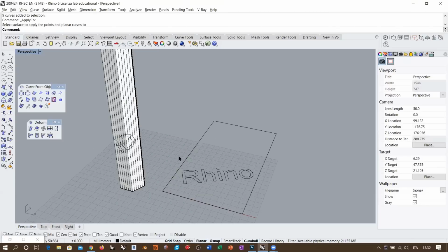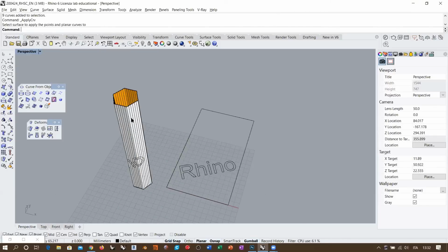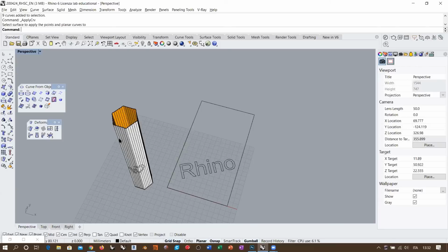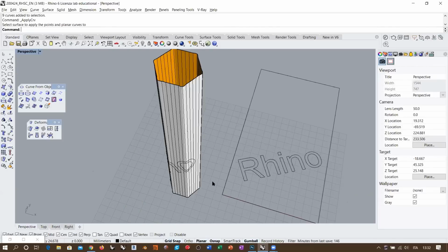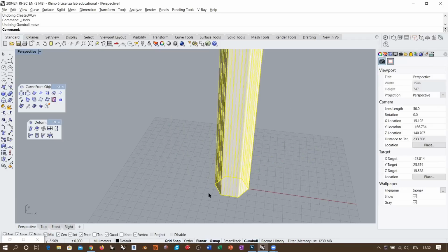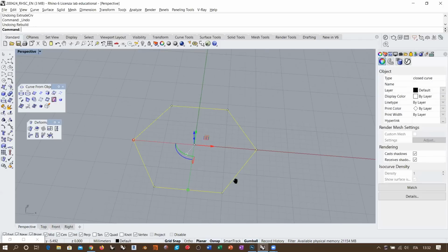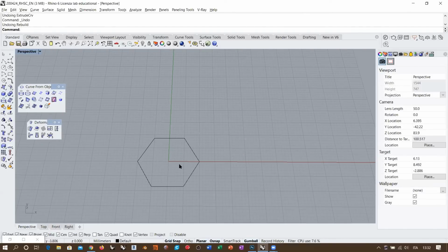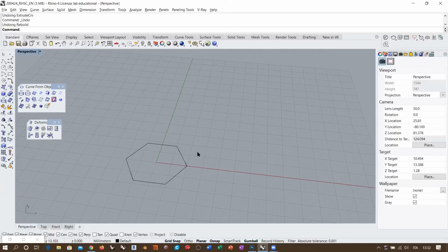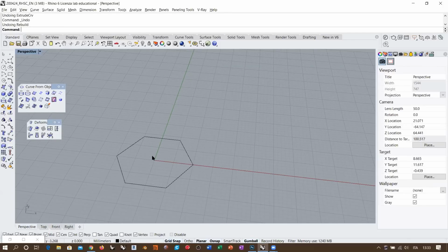But this is something that is actually altering the topology, the shape of this surface. If I want to be more precise with the hexagonal shape, I would go back to this, and instead of rebuilding this thing, I would simply create a smooth connection between the two edges in order to have an extrusion which looks a little more hexagonal. Okay, just with some rounding, but smooth rounding along the edges.